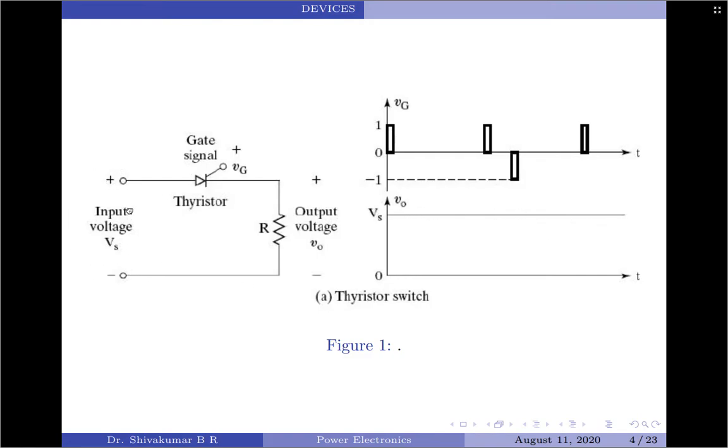If the input were AC, the moment the positive half cycle ends, the voltage VAK becomes negative, which voids the primary requirement of a positive VAK across the thyristor, and the thyristor is said to be naturally commutated. But a student should, whenever asked for control characteristics, write this with a DC input voltage source.